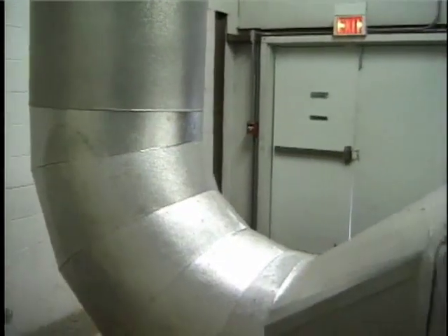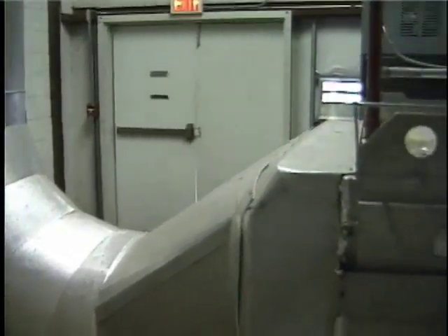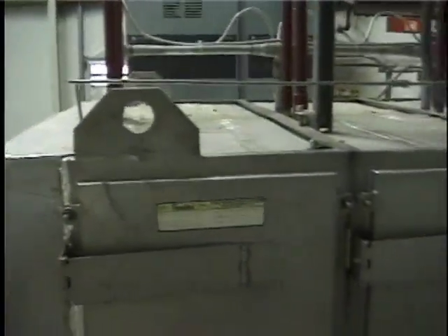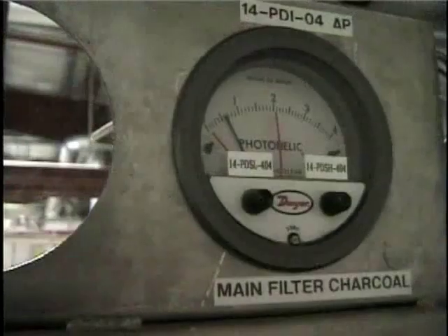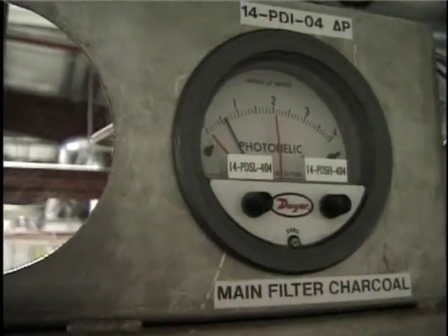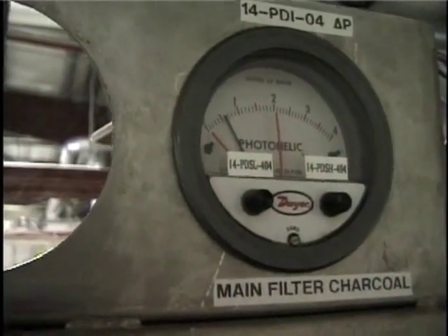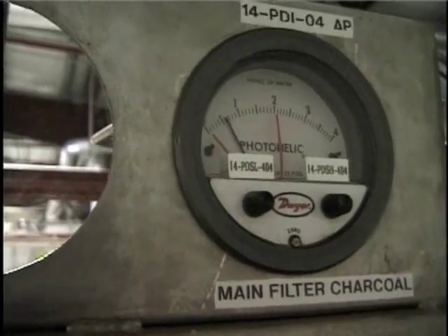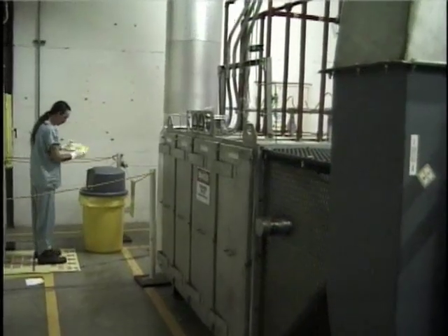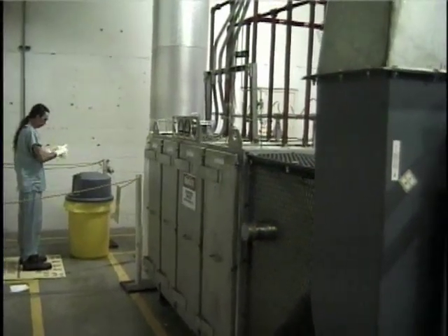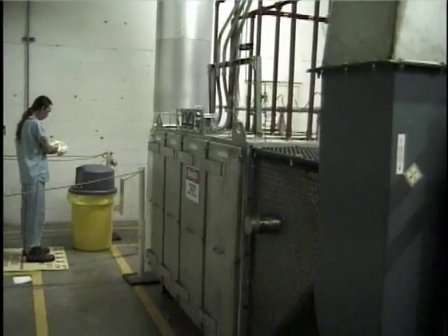The contaminated gas stream passes through the filter media, leaving the dust cake on the upstream surface. HEPA filters are typically changed when the pressure drop across the filter increases by 2 inches of water. However, HEPA filter systems may be designed to operate with pressure drop increases of up to 10 inches of water.